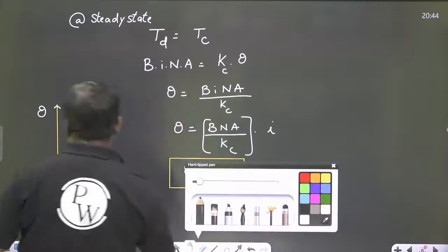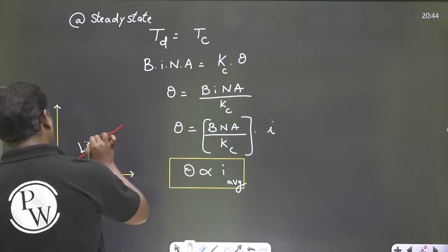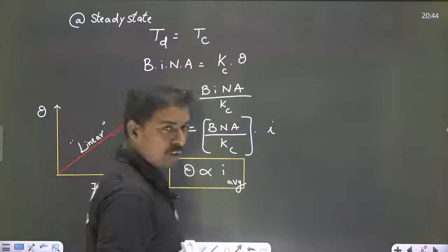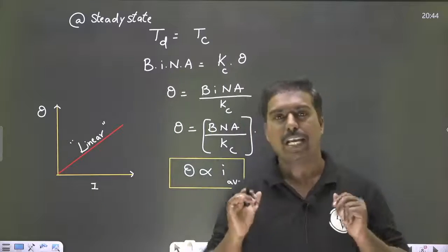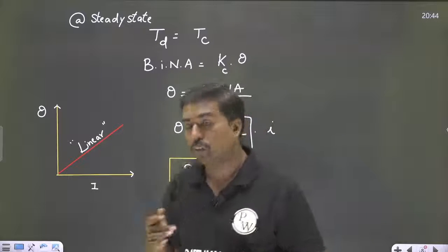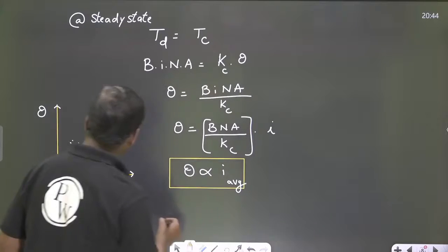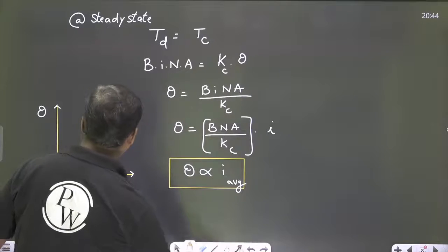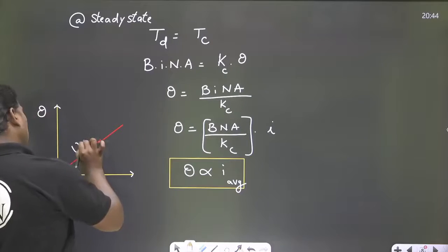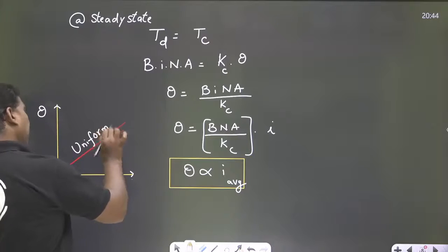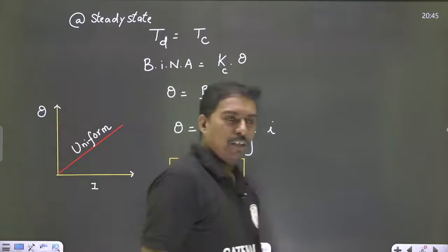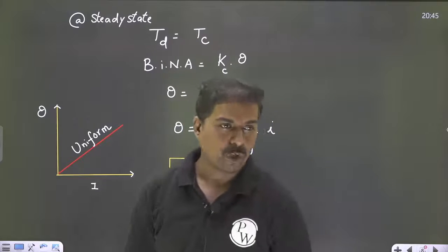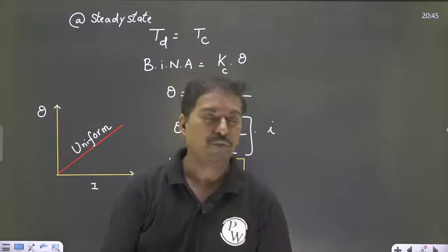When the characteristics are linear, the instrument is an absolutely accurate instrument, so the errors are very, very less with respect to readings. We call it a uniform scale, not exactly linear, because everywhere you are going to get a straight line relationship. The PMMC will generate a uniform scale. Got it?